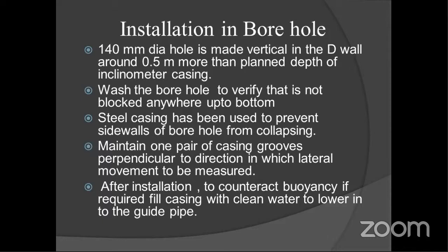The grouting should not be normal cement grouting. It should be cement plus bentonite, because the heat of hydration of the cement will be more, so it might lead to a change in the positions, and it might bend the PVC pipe, because it will generate more heat. So we are going to add bentonite. Bentonite should be in a 2:1 ratio, so that we can easily minimize that heat of hydration, and it will be good for the future.